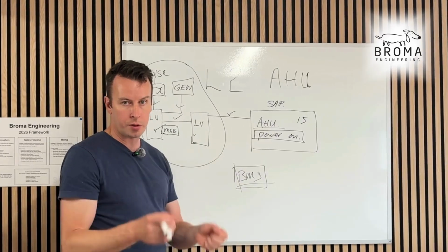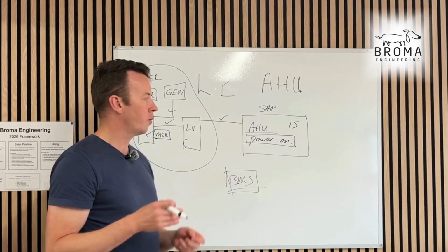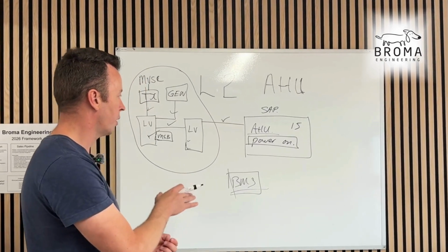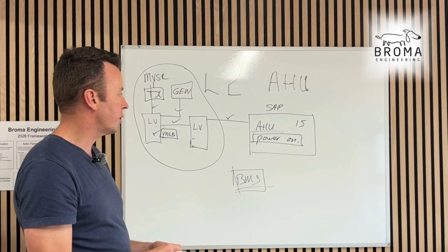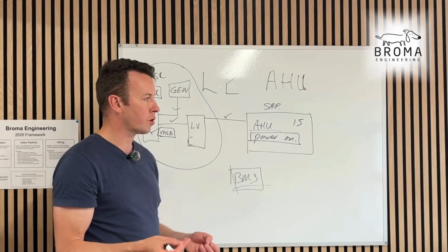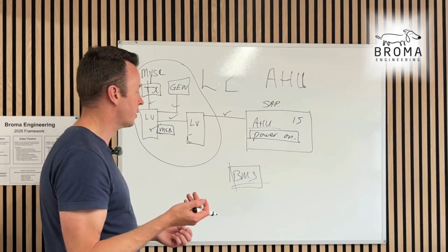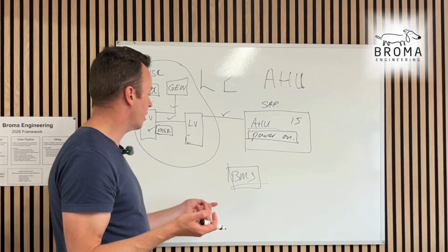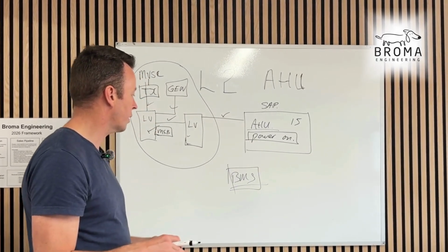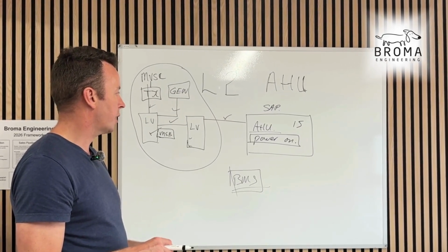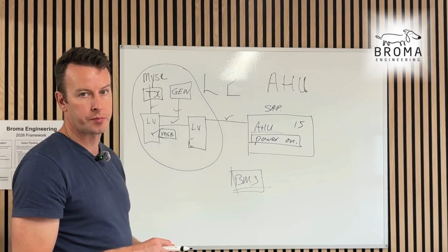We keep talking about it to everyone, getting everyone ready, making sure there's pre-inspections done of everything that needs to be done before we get power to this. Ventilation ductwork might need to be cleaned, might need to be pressure tested, cable testing the comms cable, make sure everything's connected and working right in the BMS, and that everything is intact and clean and ready to go.